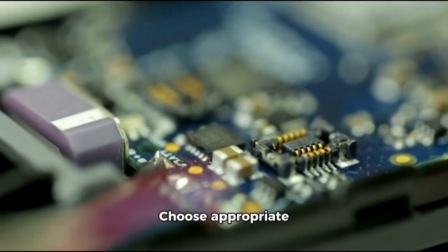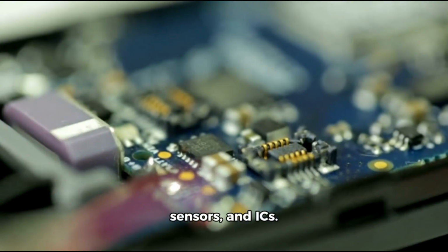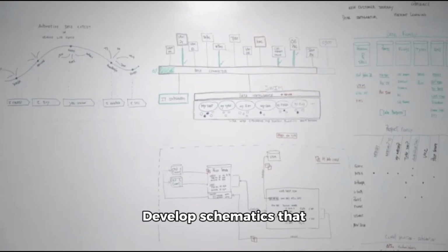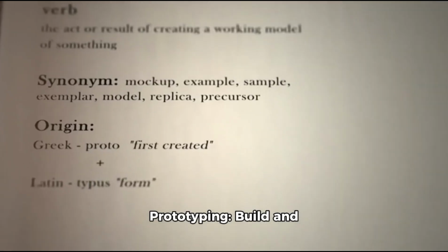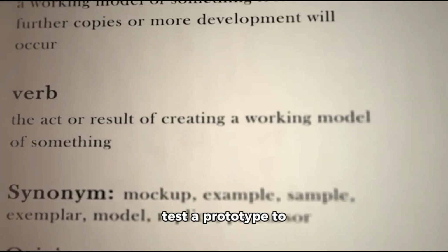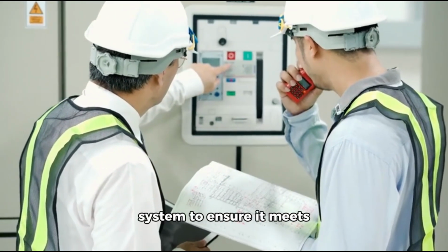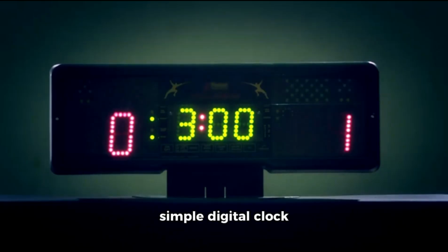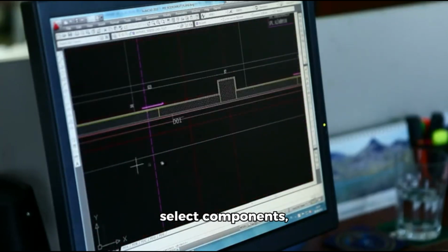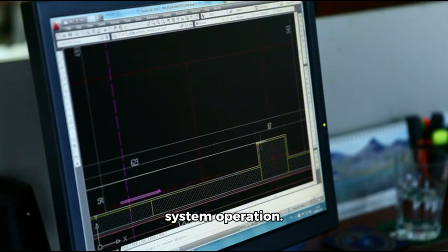Component selection. Choose appropriate components like microcontrollers, sensors, and ICs. Circuit design. Develop schematics that represent the connections between components. Prototyping. Build and test a prototype to validate the design. Verification and testing. Thoroughly test the system to ensure it meets specifications. Challenge. Design a simple digital clock using a microcontroller. Define its features, select components, create a schematic, and simulate the system operation.